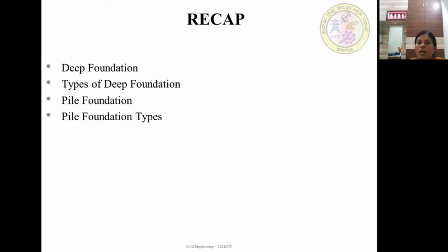Sheet piles are essential in some situations. These sheet piles are required to prevent leakage of fine materials and water. They are used in retaining wall construction, and they protect structures from shocks and vibrations. They protect river banks from erosion. These piles also retain the sides of foundation trenches.